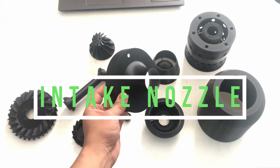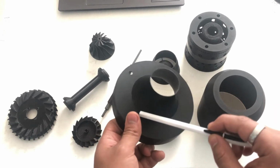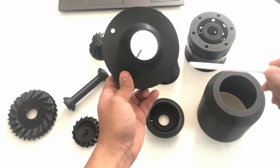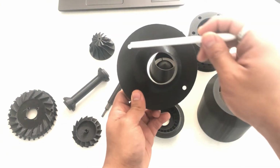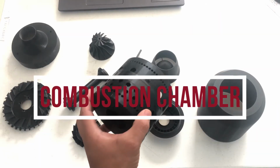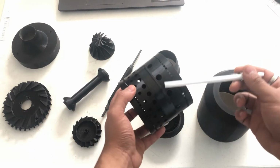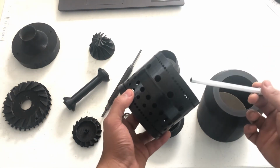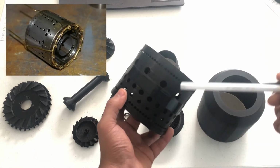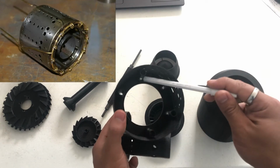The intake nozzle. This part is responsible for maintaining the air. Often auto control circuits can be mounted here. Look, that has holes for the oil and kerosene pipes. The combustion chamber. This is where the magic happens, because the kerosene is injected through the pipe. The drops are pulverized into small particles. Then they hit the wall and are redirected towards the turbine.